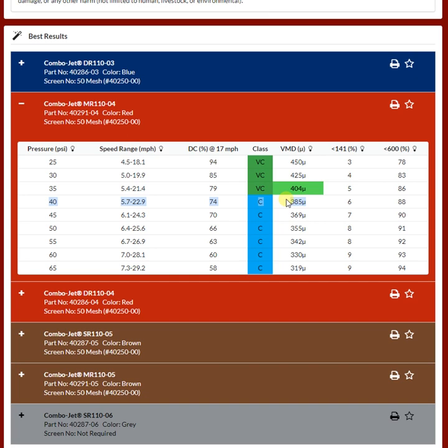If conditions are optimal, so an ideal spray day where you have a troublesome spot in the field that does have more greenery, or you want to have a little finer spray, that's when you can press a button in your cab, change your pressure on the go, and you might bump up your pressure. So you still want to make sure you're following the requirement of the spray chemical label, even at any operating pressure. But nonetheless, we'll qualify the spray tip at 40 psi, as that might be our typical application requirement.